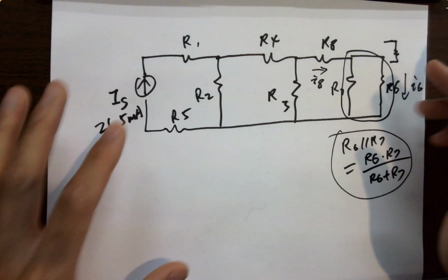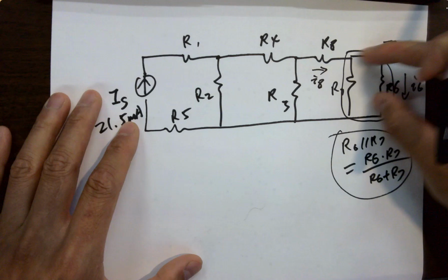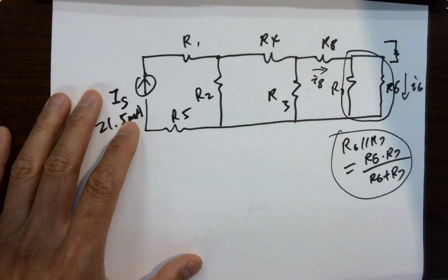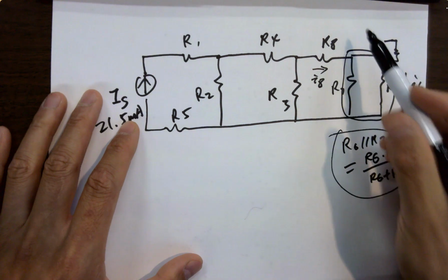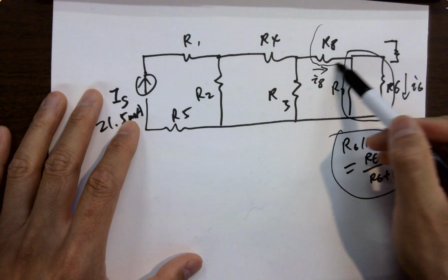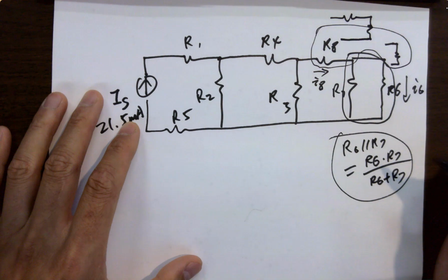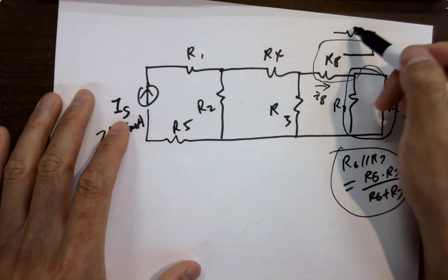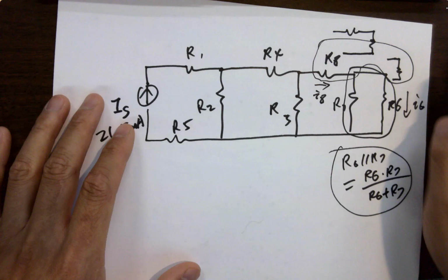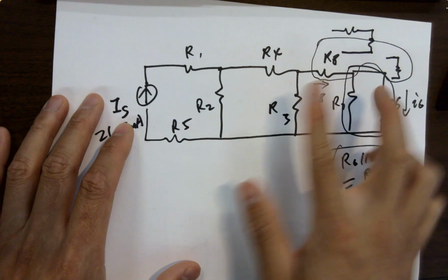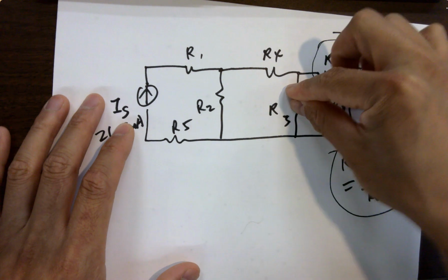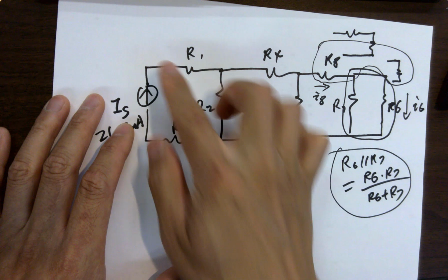This resistor will replace the two parallel resistors and connect to here. You put that in series with this one, right? And then these two will be in series. You add them together and you combine these two into one. So like parallel, series, parallel, series, parallel, done. Three in series.